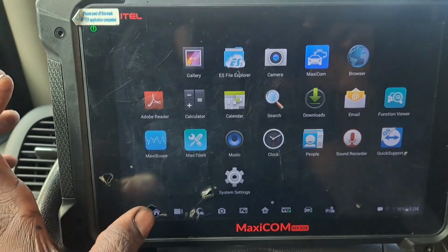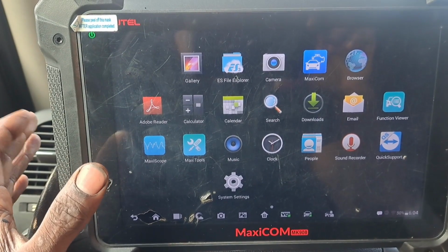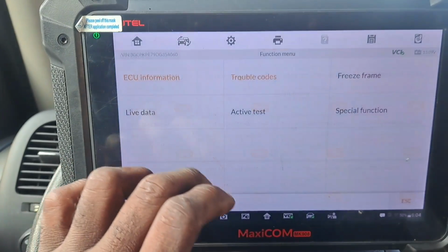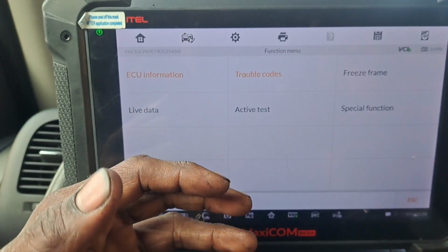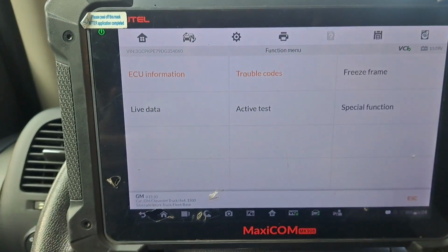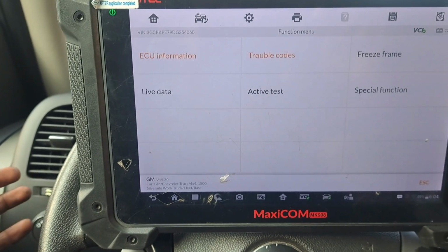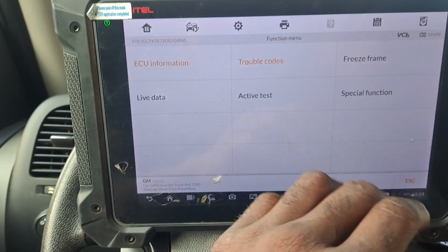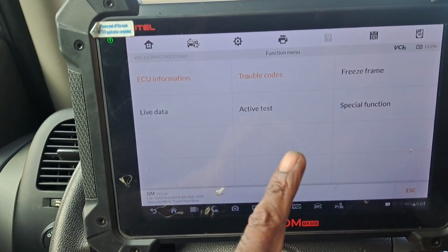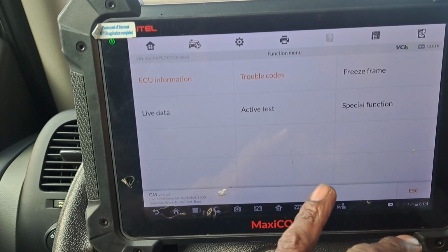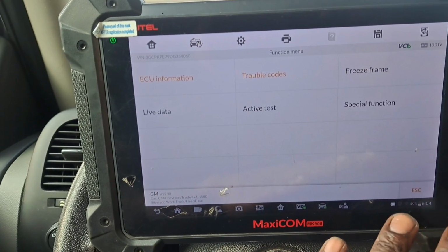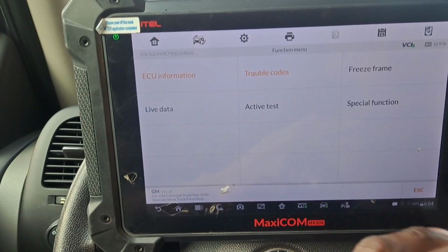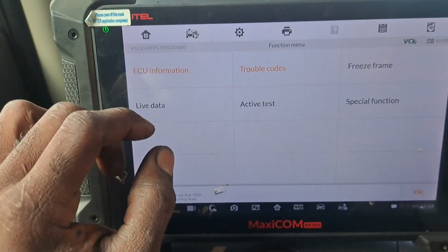It seems to be more prominent during a transition into normal operating temperatures. So when it gets hot from 0 degrees basically up to 100 or 200 degrees, in that heat soak phase, in the higher temperatures, that's when it's more susceptible, it seems. So I'm getting a little further. We know what cylinders we're dealing with, and we know that when it's hot, like right now, I can drive it and it's not going to happen. But when it sits for a while, it's more susceptible to misfire, and it's going to generate that code.